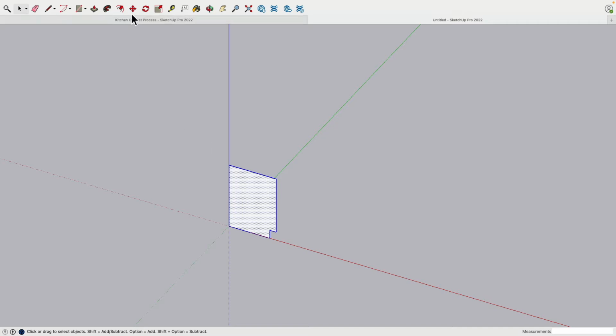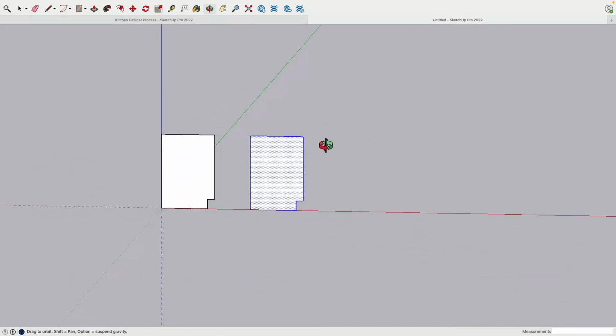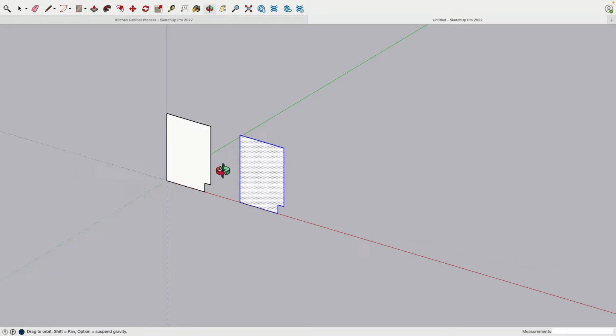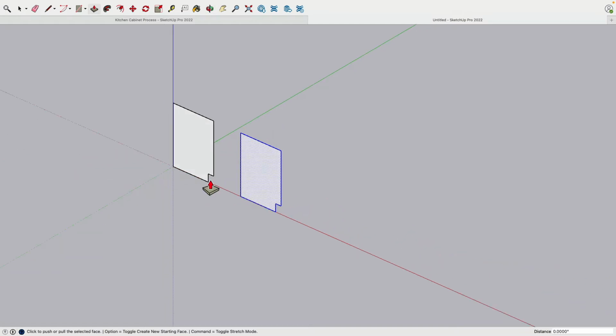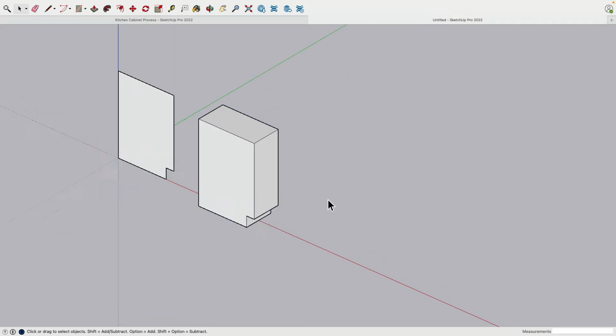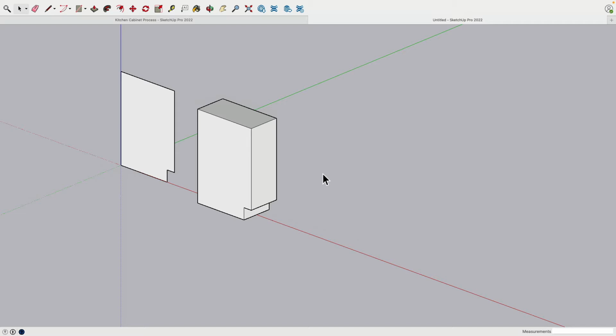Okay, so let's make a copy of this 40 inches to the right side. Essentially now I created this basic volume. So the whole thing should be around 1 foot. So I can push and pull 6 inches one direction and 6 inches the other direction. I have here an extra line, which I'm going to remove. There we are. Very good. This I will triple click, make a group. Very nice. So that basically defines the volume this unit will occupy and use.